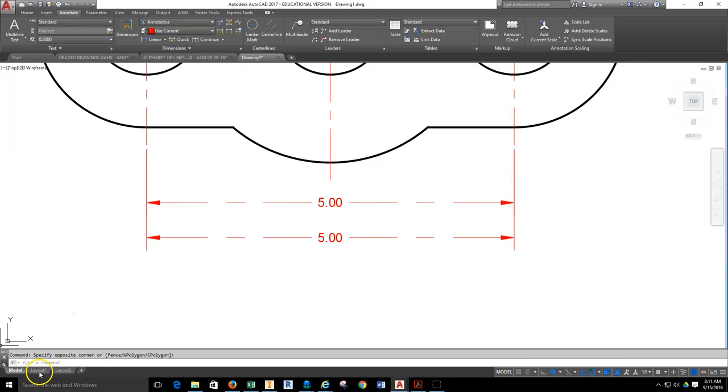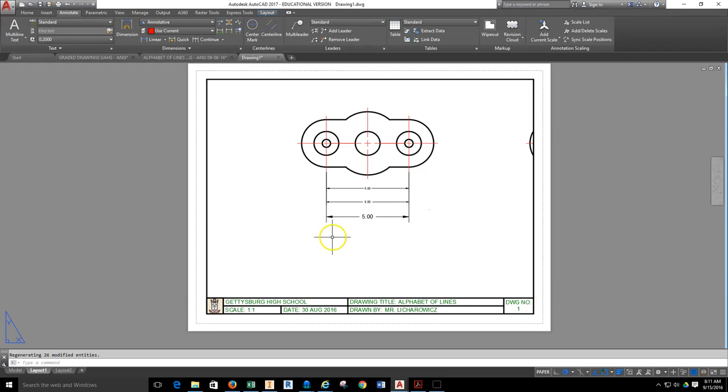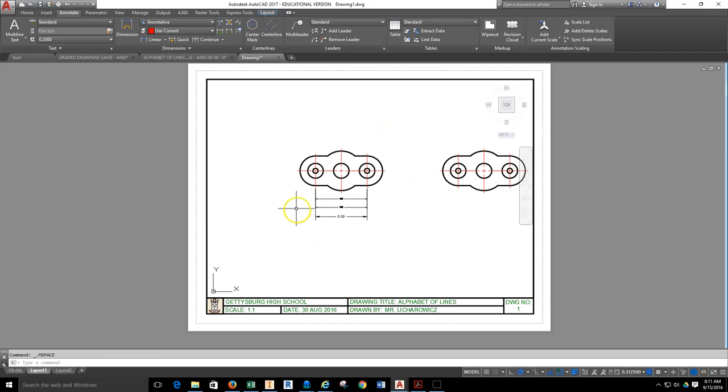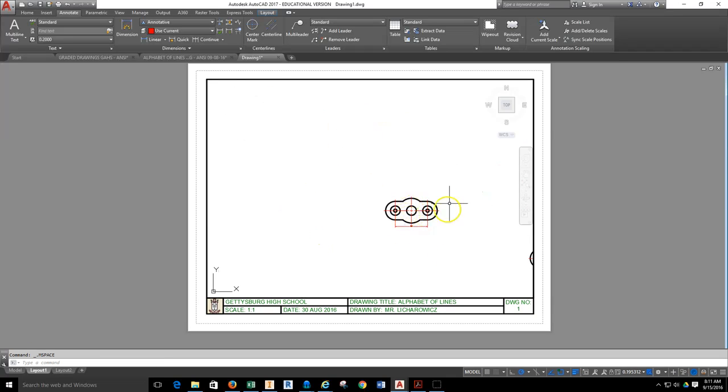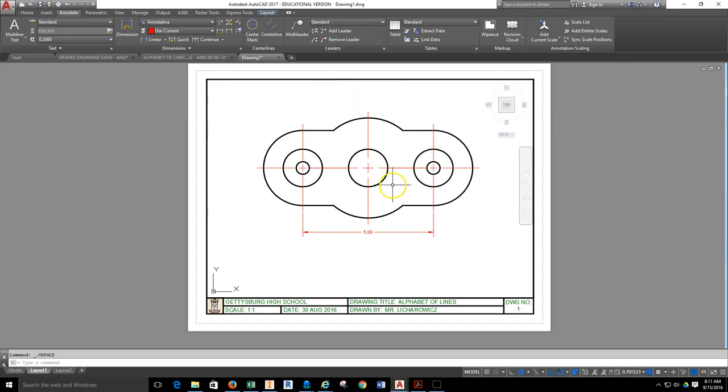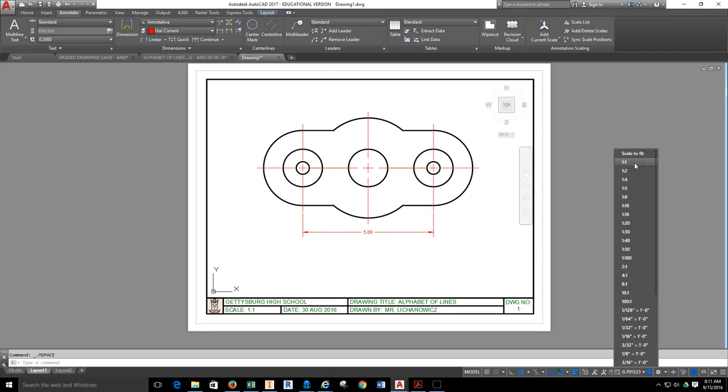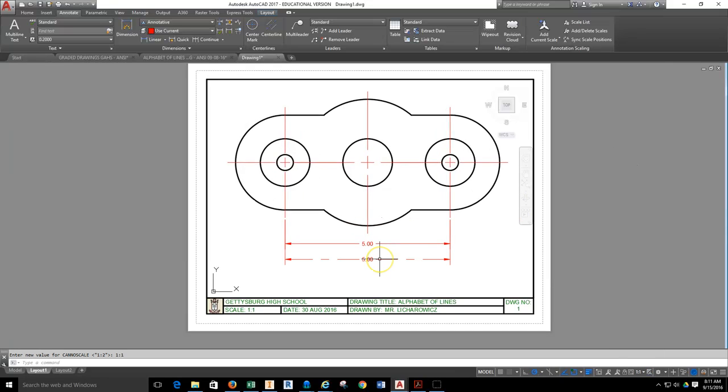Alright. This is where we get into the magic. I want you to go to a Layout tab and make sure that you can place this onto it. It doesn't have to be a title block. All it has to do is be a viewport. I want you to be able to scale this drawing so that it is scaled 1:1. Watch what I'm doing here. When I scale this 1:1, I'm going to have a second dimension pop up.